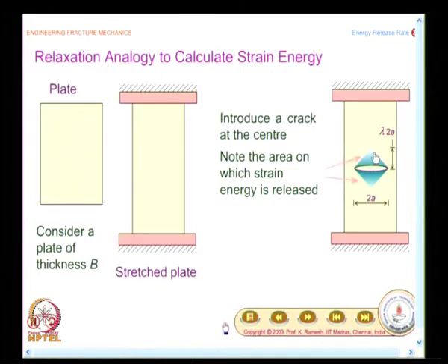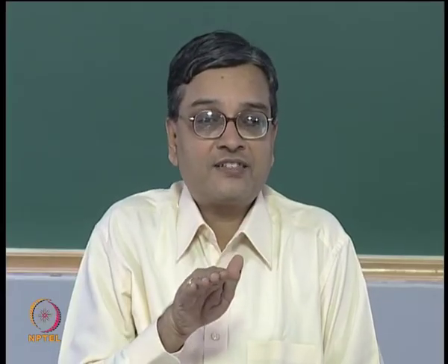So, the focus is only to understand that the strain energy of the system decreases to form two new surfaces, and that is the reason I also mentioned what is logical is when a crack extends by itself. When we found an identity between K and G, we did it very systematically. In fact, that is much more appealing to develop the energy release rate.